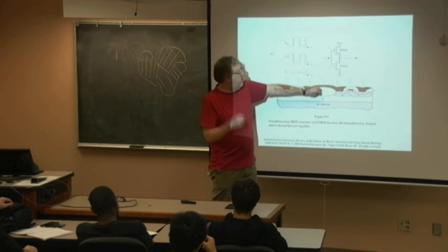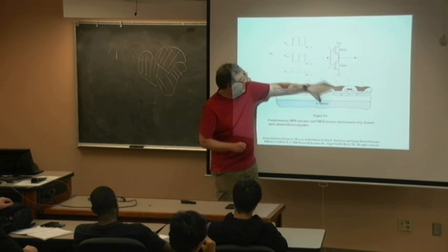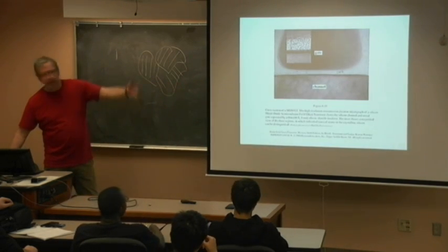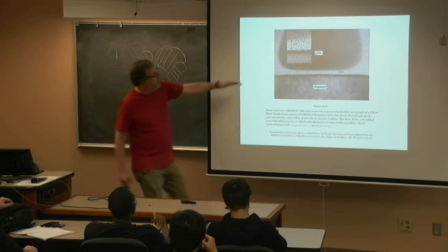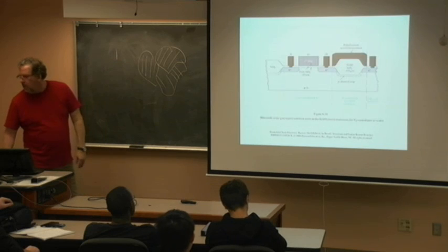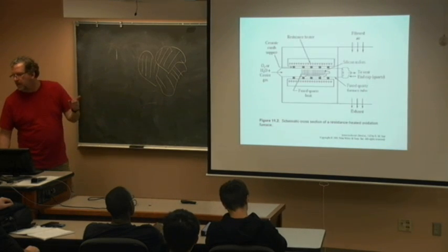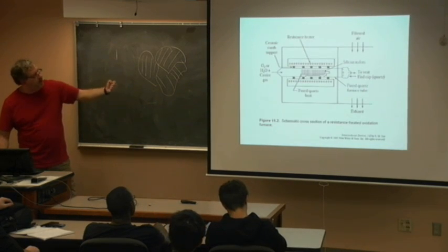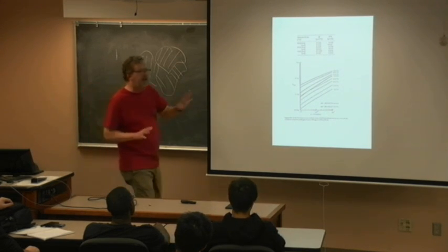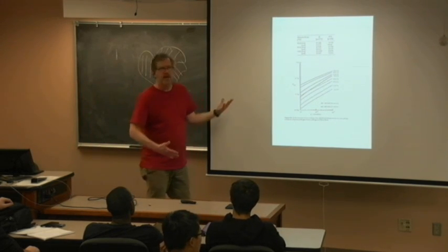When you add water, it oxidizes at a faster rate, so you see it balloon up. And so this is the thin gate oxide of high quality, so we grow this in a dry ambient. We put it in the reactors, we grow it. But this is really the take-home kind of stuff.